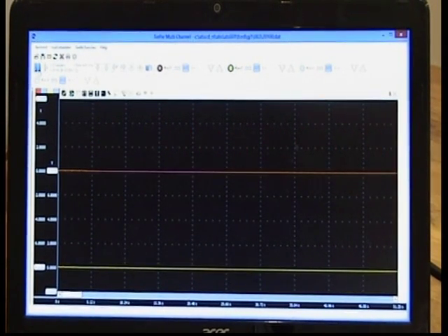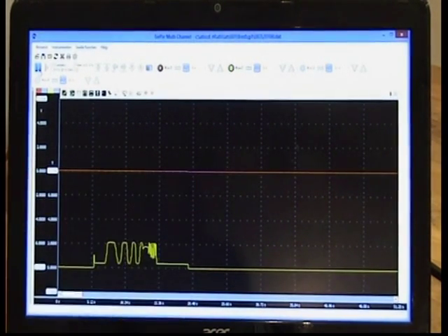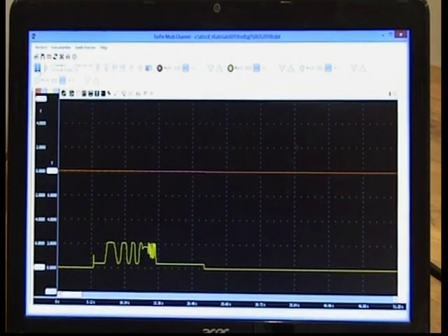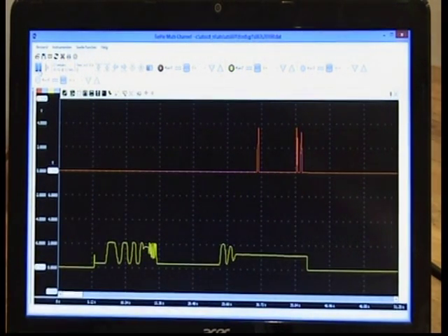So I switch on the ignition. Let's see. Okay, the second track is working okay. And the other track I connected to the ground, so that is 0 voltage, and I start the engine and see what's happening. On certain RPMs you see there's a problem there because the voltage is going up on the ground wire, so we have a problem there.